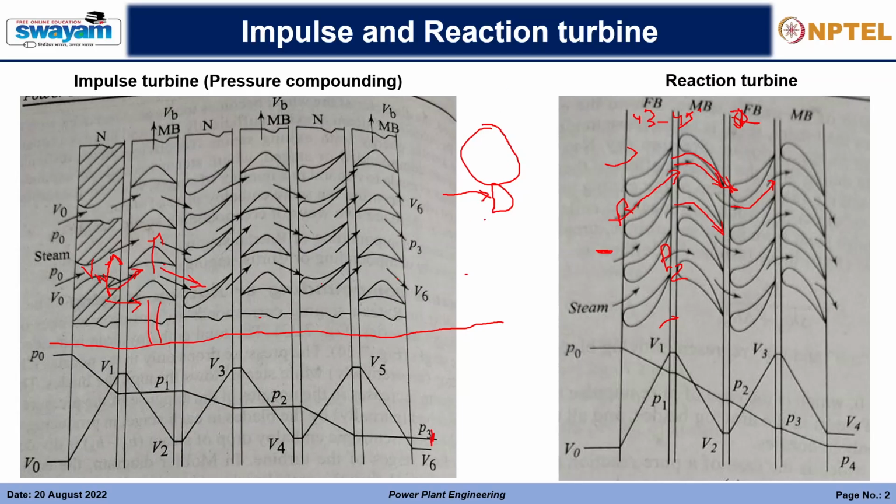So here it is like this, but with this turbine, you will read about this kind of turbine in more depth in the next class videos. Here the jet impinges directly in the tangential direction, but in this turbine it is impinging like this. Due to this there will be a whirl component at the inlet, Vw1, and a flow or axial component, Va. The whirl component is responsible for the blade velocity Vb.